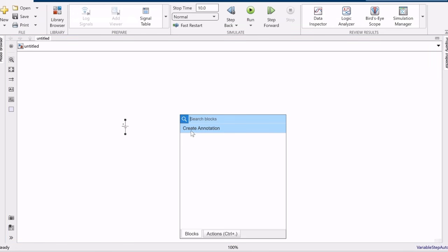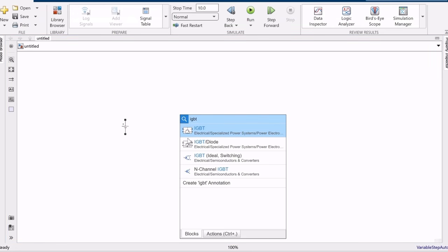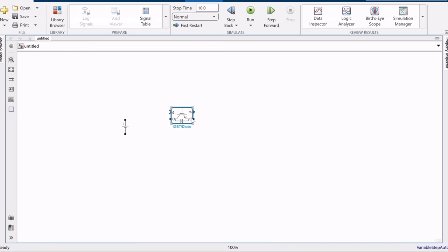And then we can use an IGBT. I will use those with diodes, so it works in both directions. So we can just connect that to the battery, to the DC link voltage, the input voltage. And then we have another that we connect also to the DC link voltage. So now you can see that we basically have the topology that we want.